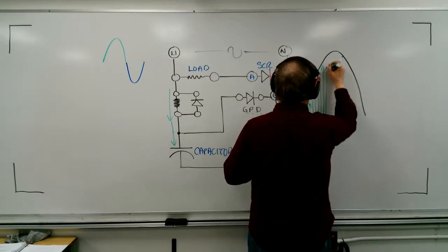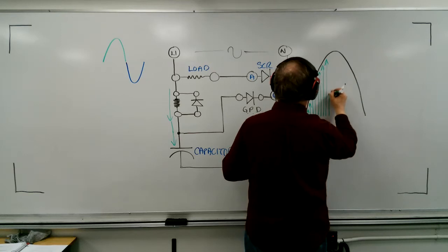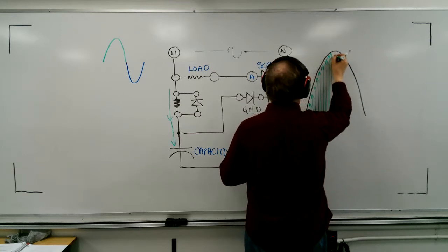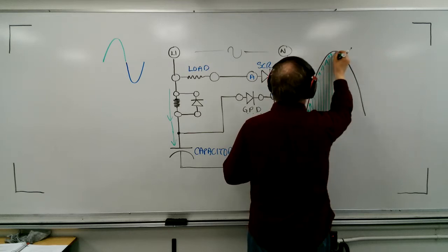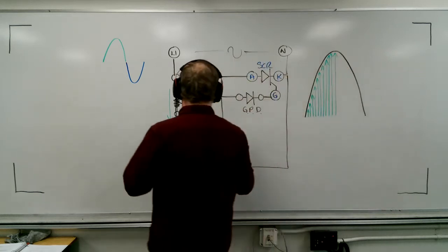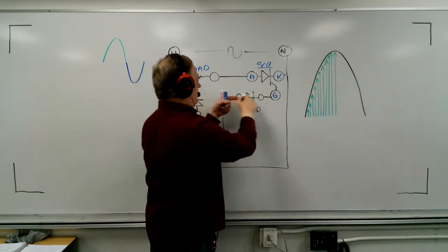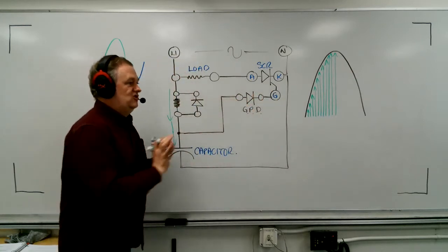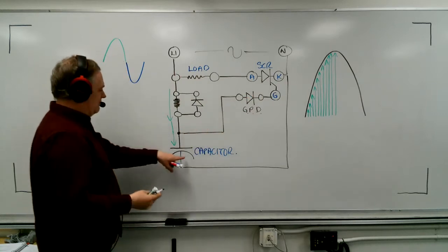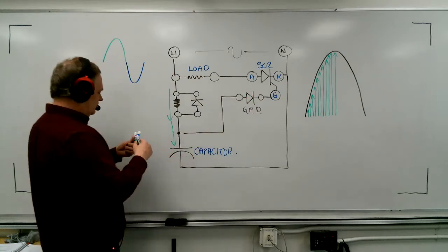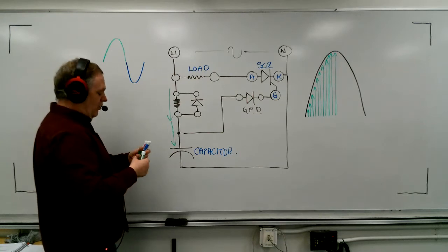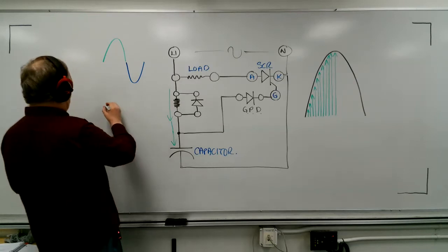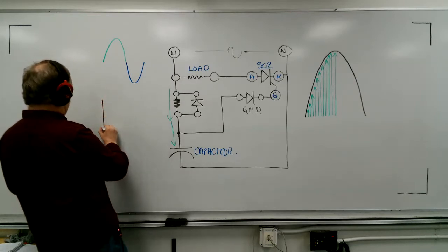Okay, current's getting larger and larger. In other words, the rate that the current is flowing is rising higher and higher. But here's the thing. What does it take to actually get a trigger pulse to flow into the gate? Well, we have to build up some voltage to shove it in. And some of you may remember, I'm going to show you a graph of how a capacitor charges. And your voltage and current look like this. Here's the capacitor, okay?